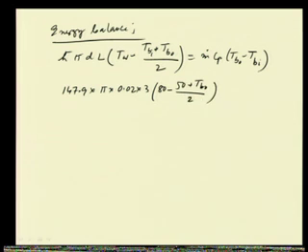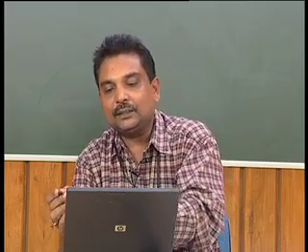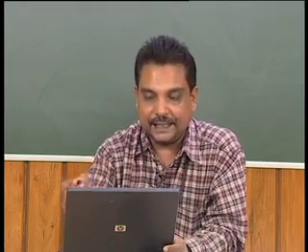We would like to find it. This is equal to m dot, which can be calculated as 6.22 into 10 to the power minus 3, into (T_bO minus 50), and we are writing all in Kelvin because we are finding differences in temperature. So, Kelvin and centigrade does not matter. We are writing all the temperatures in centigrade, into C_p equal to 4180.